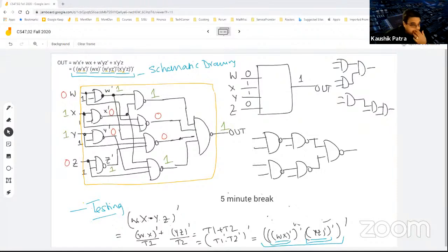What I'm trying to do here is show you an environment where we can define this logic circuit, and test it, and look at the behavior of this logic circuit. That is called a hardware simulation environment. And we use a specific tool called ModelSim.